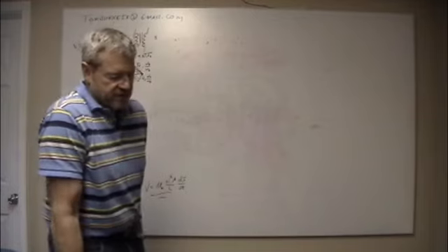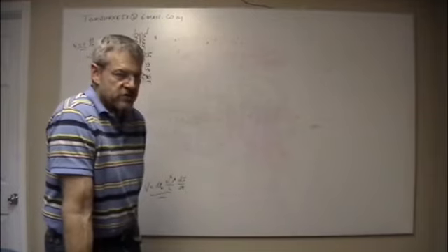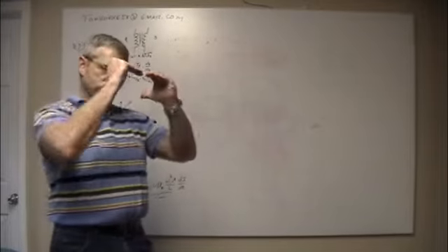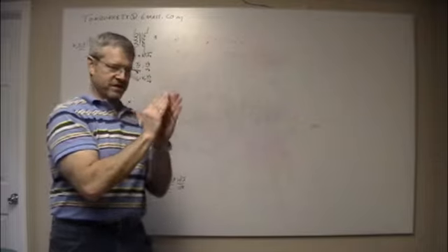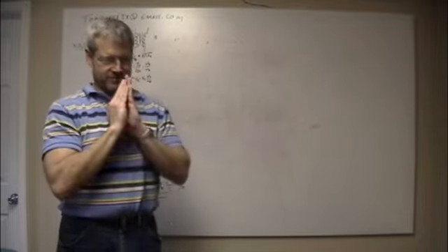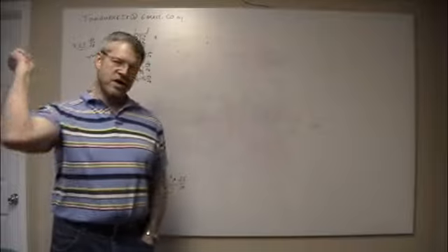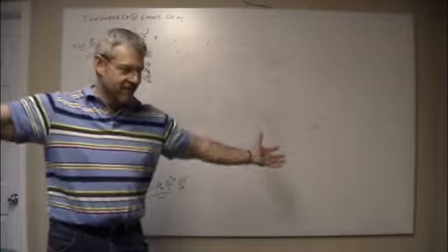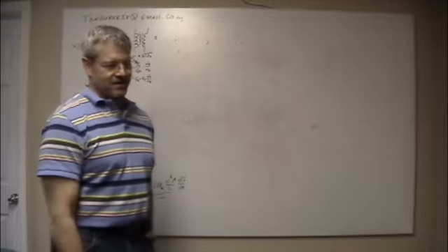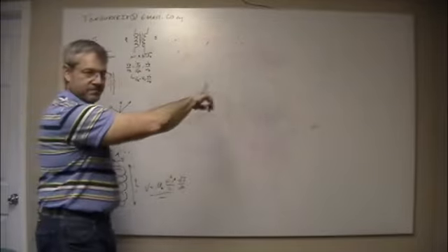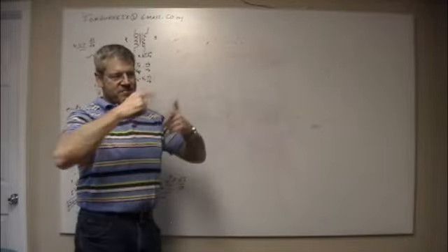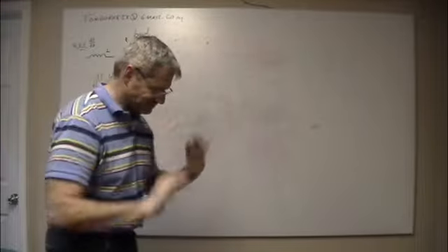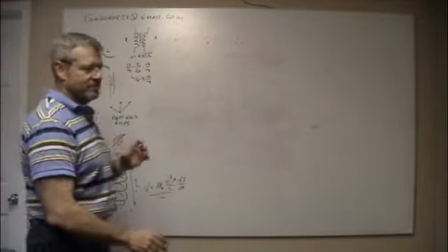The thing is with cable TVs, though, they're running so many signals on there. They're narrow. They're really sharpening the bandwidth. So you've got a signal at 300 megahertz and another one at 310 megahertz and another one at 320 megahertz. And one lousy radio station can come in and hit that and knock out 5 channels on your TV set, right? And then when you hit these nonlinear transistors here, they beat and they'll make other parasitic signals. And so, yeah, you want to keep it out, but